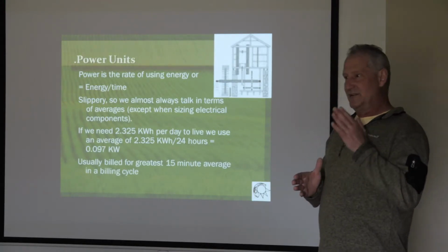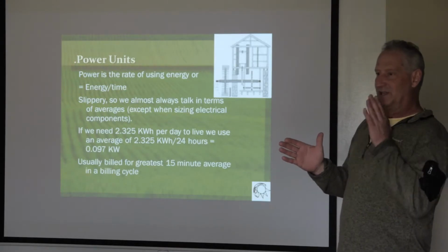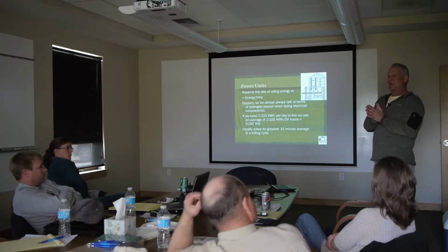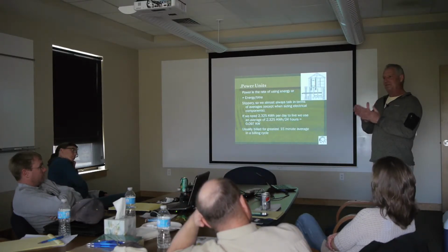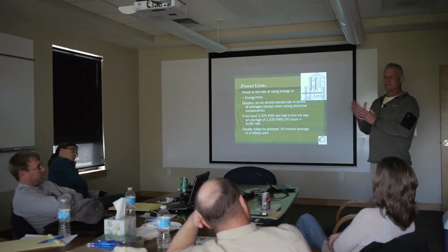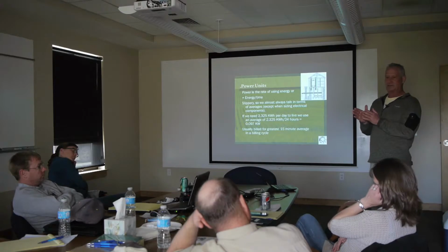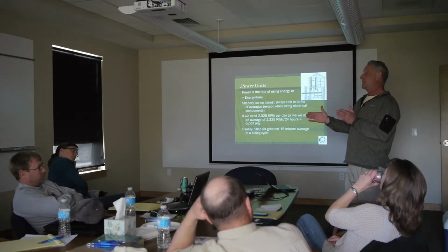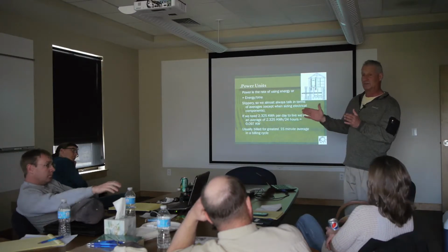They read a demand meter, then reset it to 0. Then the meter watches each 15-minute interval, and it reports the biggest power use going through that meter until the next time the meter's read.